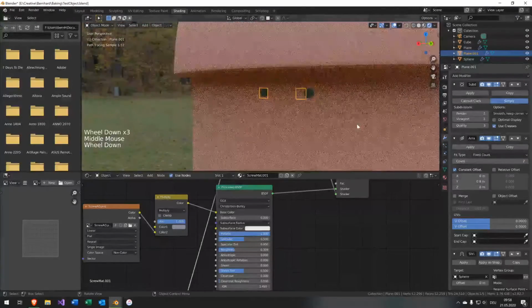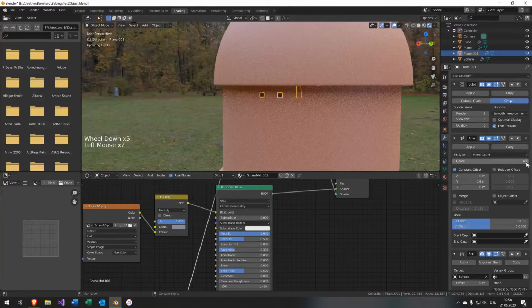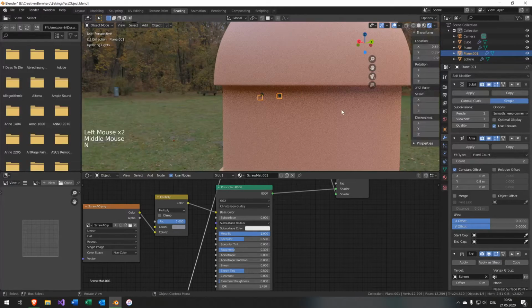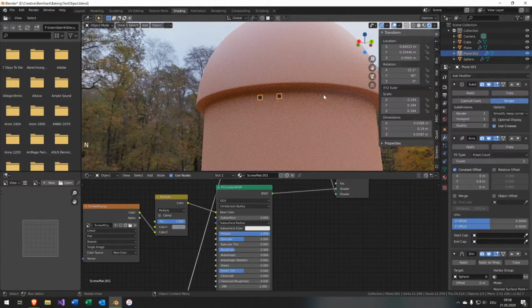It looks good, but I already see it's turning up somehow a little bit. So if I increase the value now, it's snapped to completely different spots by the shrinkwrap modifier. And this could be due to the wrong rotation and due to wrong calculations here. So I can try to reset the rotation, but I guess it's not helping that much.